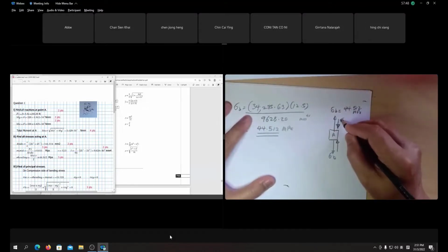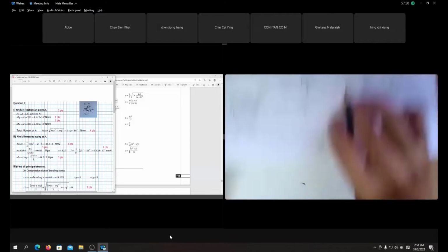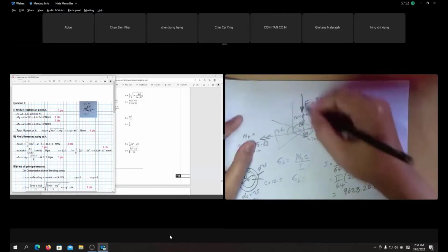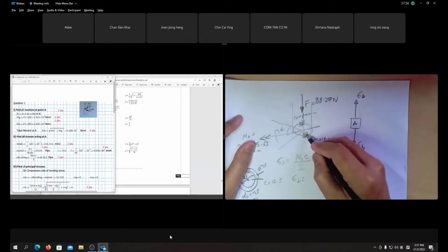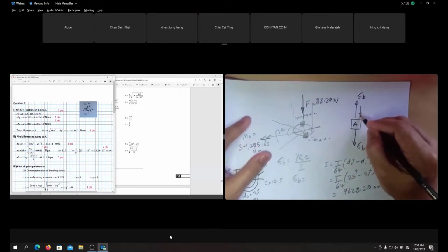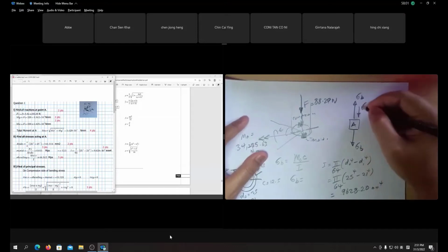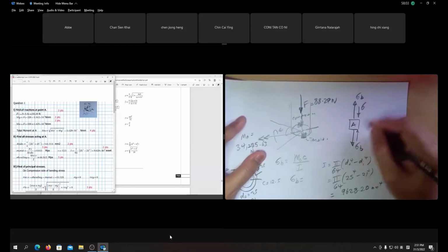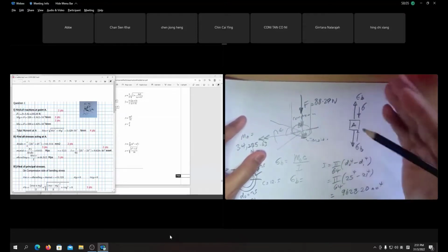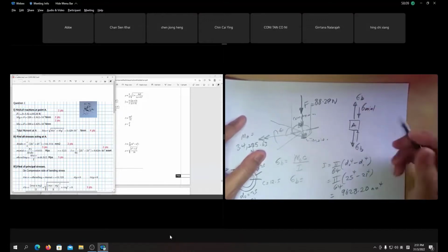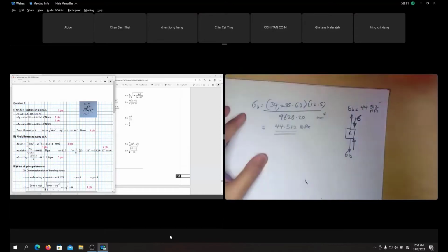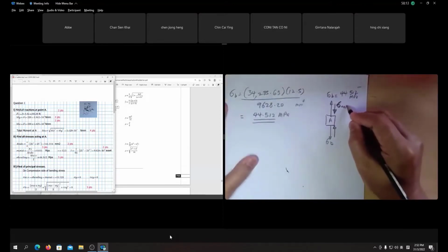What sigma is this? From that 88.29 force down, what does it produce on the element? What type of stress is that? Direct force. What stress is it on element A? The upper portion goes compress. Is it axial stress, bending stress, or torsional? Yes, you are right, axial stress. So at A we have sigma axial.